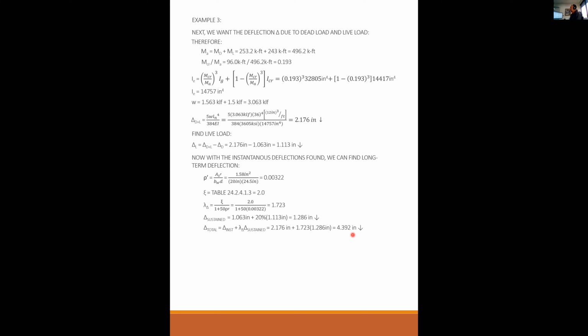Okay, but it may be completely failing the acceptable criteria in terms of deflection, and that's absolutely true. This 4 inches did fail the acceptance criteria for deflection. I just wanted to be clear that the building isn't on the ground. It hasn't collapsed. It's just not usable because it's got too much deflection in it.